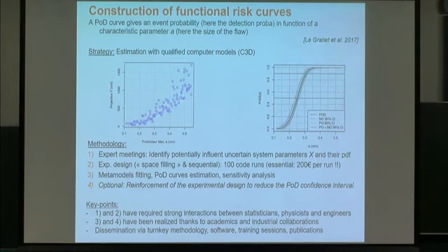Here we have used a Sobol sequence for the space filling design, but I think this phase can be improved by imagining other designs, like a Latin hypercube sampling maximin design, but with some sequential property. Sequentiality means that you have defined your design with a number of points, but if you take a sub-number of points, the first points, you again have some space filling properties.